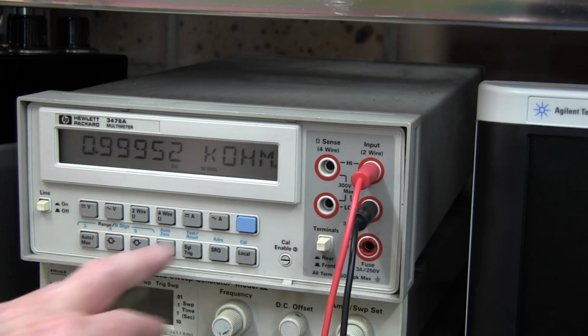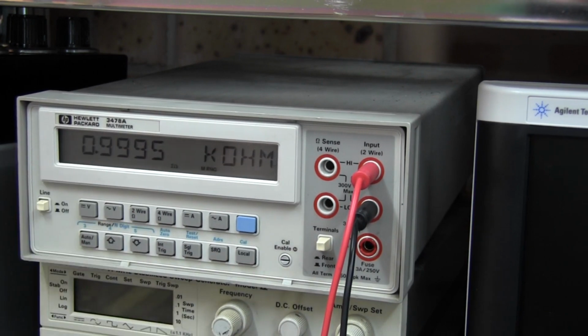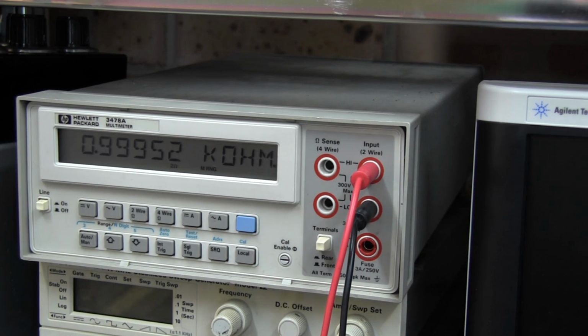And use the 5-digit mode. I mean, the 3478A has got a 4-digit mode to mimic the Fluke 87, or even a 3-digit mode if you're that way inclined. But we'll use the 5-digit mode. It's warmed up, so it's nice and stable. And the other thing which can affect this sort of measurement is the change in temperature over time. So we'll just monitor that as well. But I wouldn't expect a major change. These are fairly low ppm value resistors. They're probably 50 ppm or something like that. But I'll monitor the temperature change over the span of, I don't know, an hour it's going to take me to measure these things. The temperature shouldn't change that much.